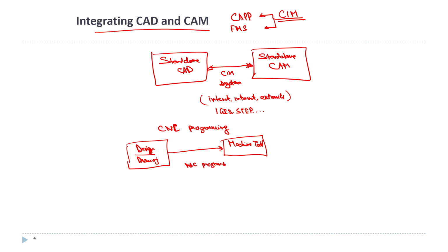When a numerical control program is taken using a computer, that is computer numerical control. When I say NC, it is just numerical control, which is generally taken using a punched tape or a magnetic tape. This is the challenge where we need to work upon the part programming. And in the part programming, the first thing is we need to develop the CAD data for CNC or NC.